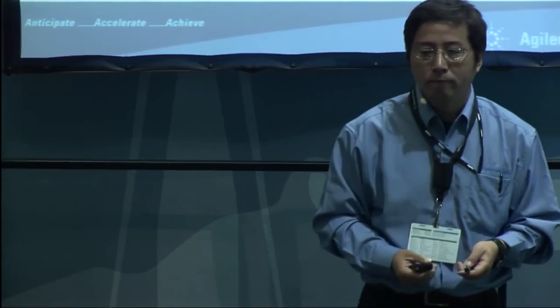How would I know if I had enough bandwidth for my length? Okay, in our instrument, all you need to do is tell it the length of your cable, give an estimate, maybe 20% more than the actual cable, and the instrument will automatically calculate and tell you the resolution. And you can look at the resolution and see, okay, that's good or not. It's pretty obvious. Other questions?